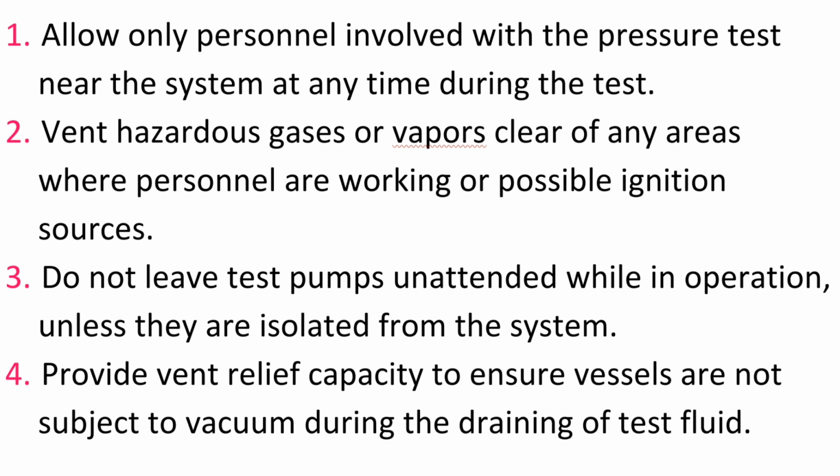Conducting pressure tests. 1. Allow only personnel involved with the pressure test near the system at any time during the test. 2. Vent hazardous gases or vapors clear of any areas where personnel are working or possible ignition sources. 3. Do not leave test pumps unattended while in operation, unless they are isolated from the system.